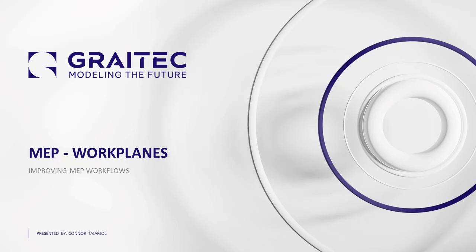In today's Revit tip, we're going to be reviewing how you can utilize workplanes to improve your MEP workflows. We're going to be reviewing how to place workplanes, and how we can place elements on a workplane. Mostly we're going to be looking at vertical workplanes, how we can place air terminals onto a wall, how we can